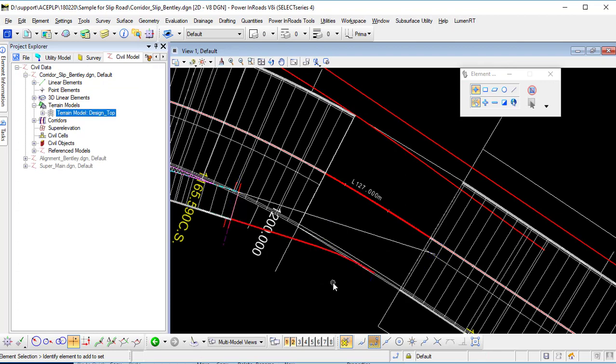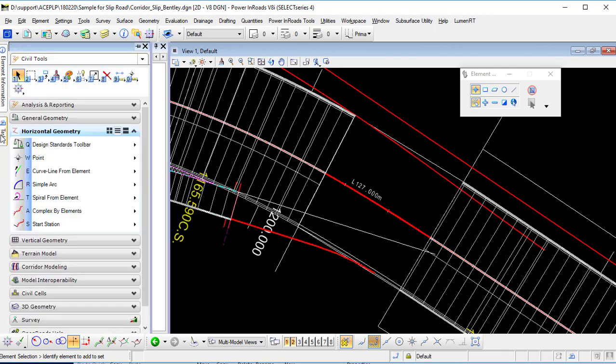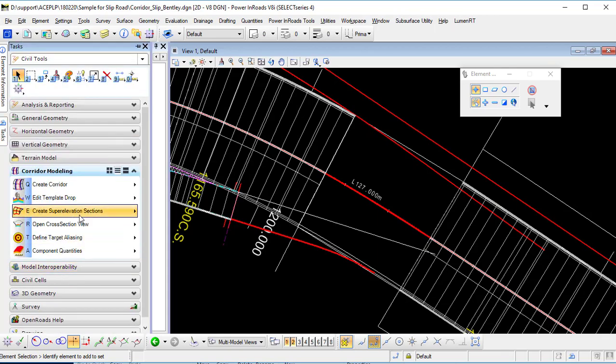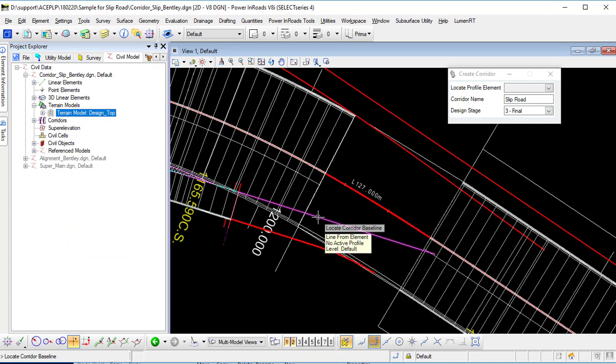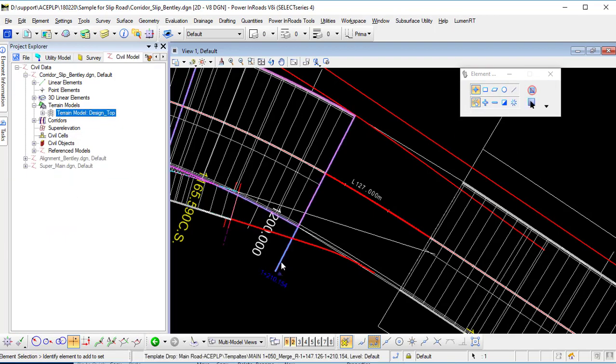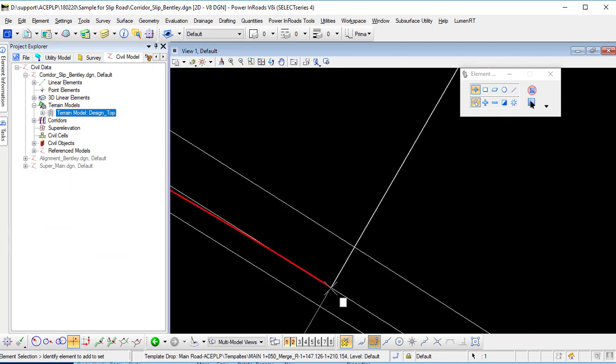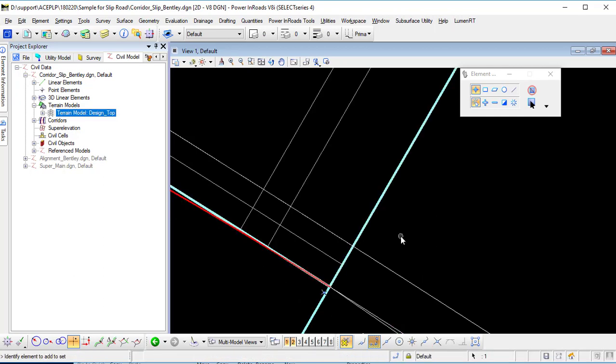So the next thing you can do is apply the geometry here. I just go back to the corridor. This is a new alignment, so I just select the new corridors. If you have a profile, remember this profile will be similar to this corridor. So I may just simply extend my corridor a little bit, just go to here, to this point.